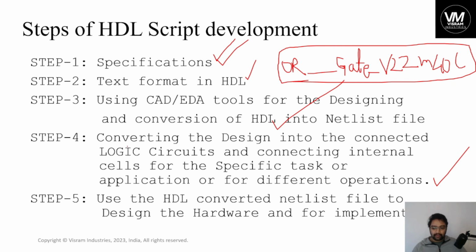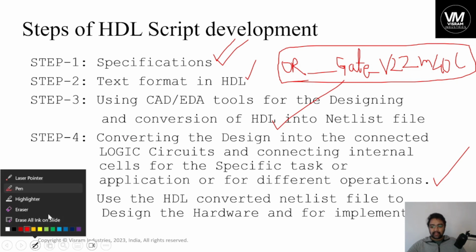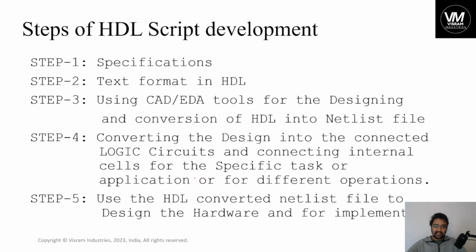The synthesized netlist file plays the key role. So now you all understand what synthesis is. Keep in mind, guys, the HDL language will be converted to a netlist that can be understood for hardware design and implementation.